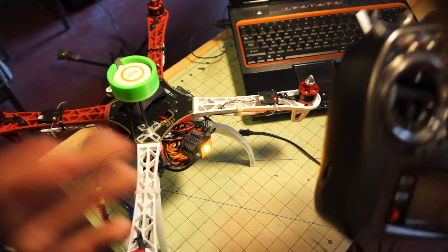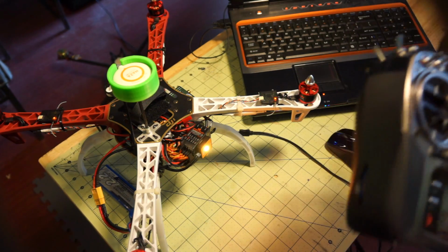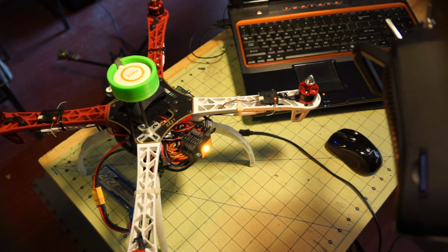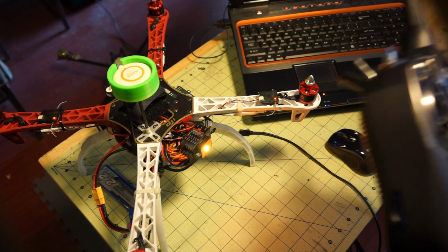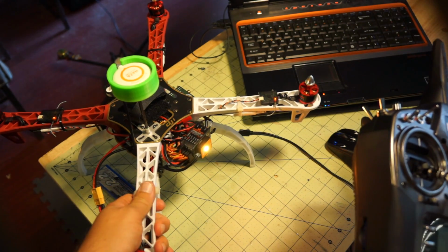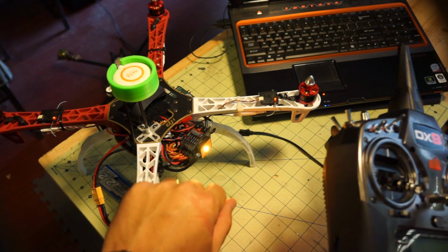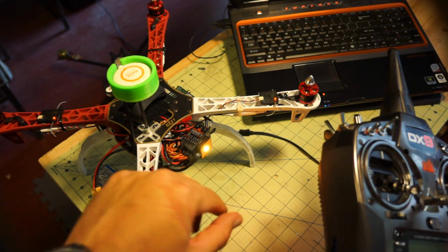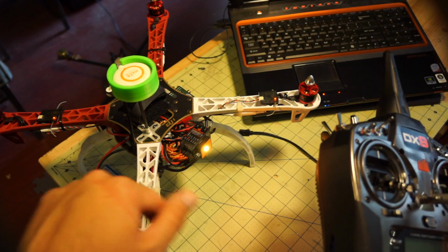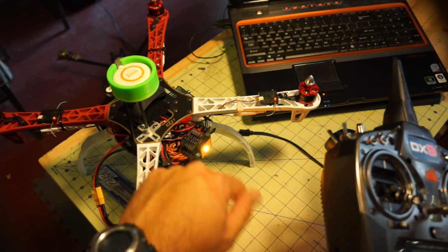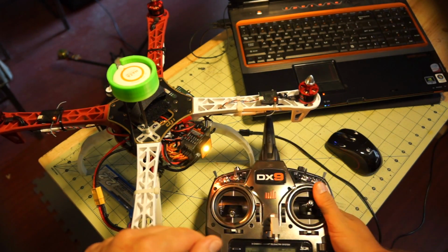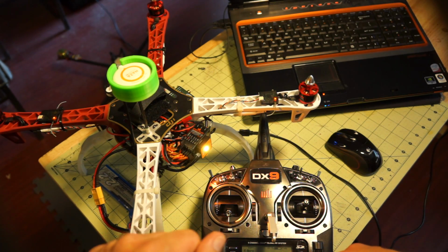We would of course be outside. Make sure to take your cell phones, your pocket knives, anything that may cause magnetic interference off of your person. Then we're going to pick up the aircraft. We're going to rotate around the axis of the aircraft 360 degrees, and you'll see the LED change to green. Then you're going to tilt the front of the aircraft down and do the same thing. And hopefully you'll get a good compass calibration.